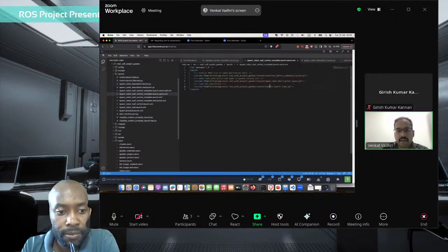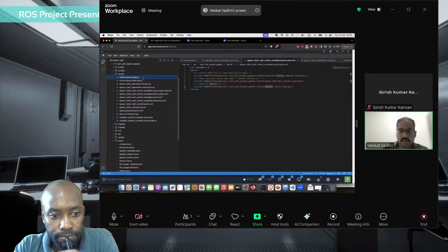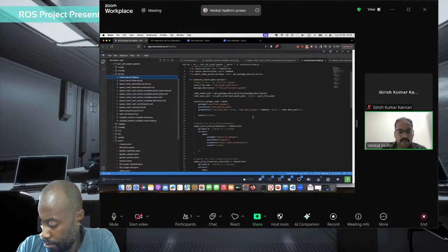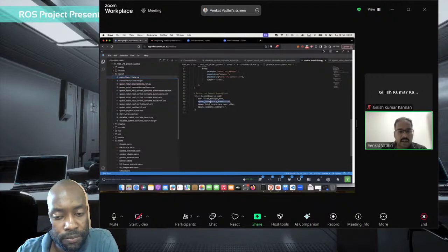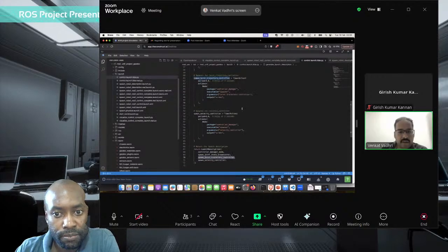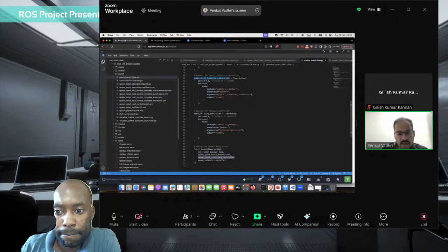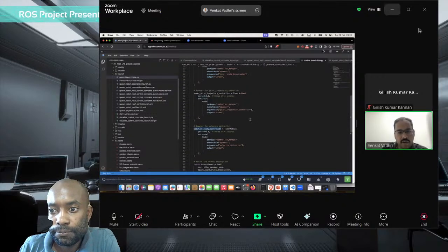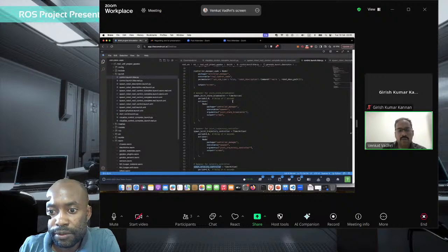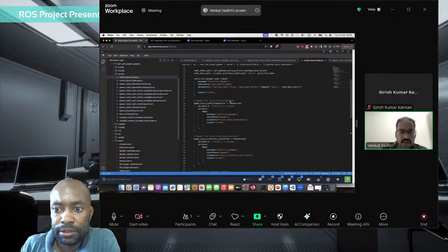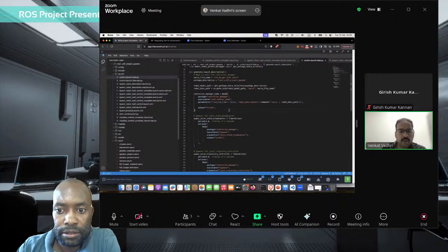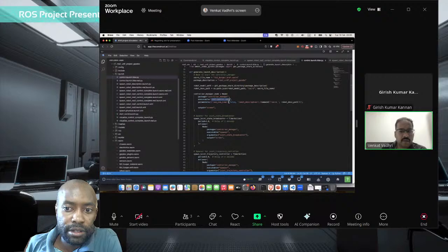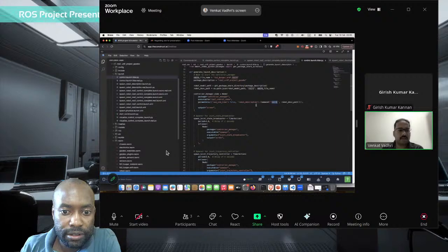The third file is the launch control file, which is this file. Its main purpose is that it spawns three things. One is the joint state broadcaster, which keeps broadcasting the joint state when there are moving parts. There is a trajectory controller, and then a velocity controller. These are the three controllers we spawn for the three plugins you saw loaded. This is required for the movement and keeping track of where the robot is, and a control node to do the rest. We give the Xacro file saying that here is your Xacro file, and then you launch and control the leader.